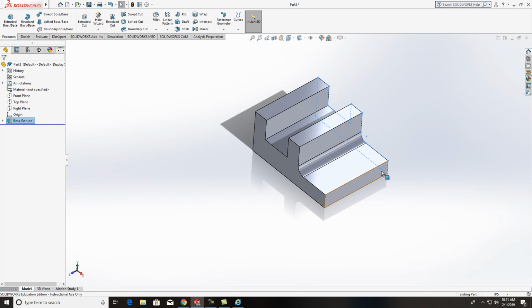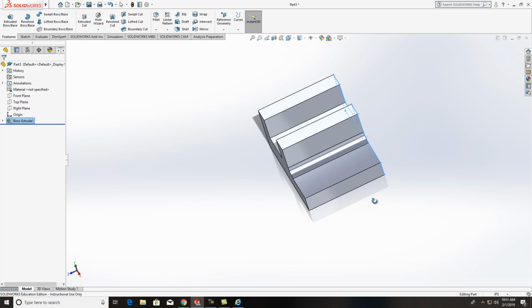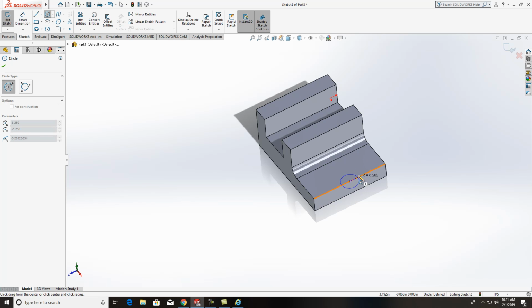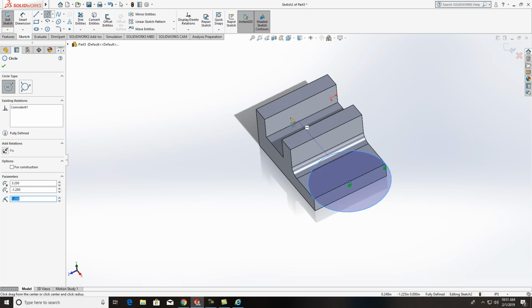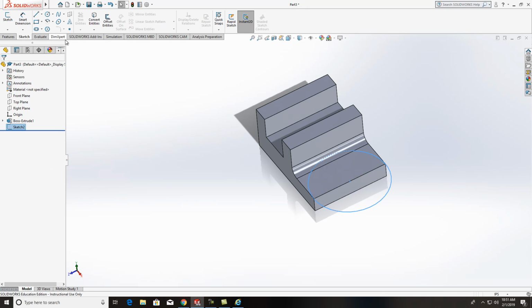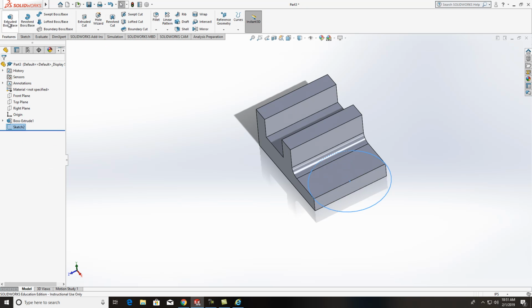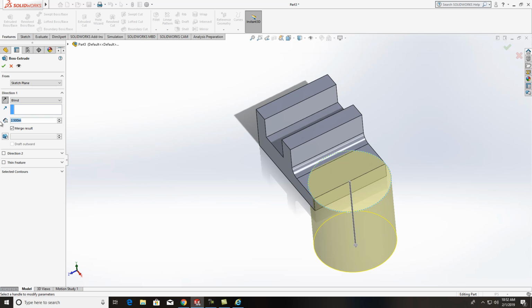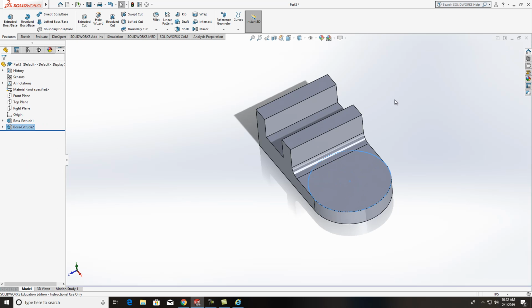And we got to put this round piece on here. So again, let's come up here to sketch, and sketch, click the face of that, and I'm just going to go up here and grab myself a circle, center radius. I catch the center of that, bring it out here and touch that edge. That should be right on the money. Exit the sketch, feature mode. Grab that, and I want to flip that around, going down that way, and also this is a 1/2 inch deep. Finish it with checking your check mark.